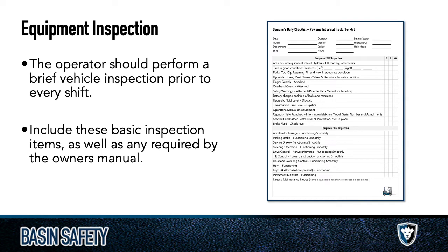All right, equipment inspection, vital. This needs to be done every day prior to the shift. If you have 2 shifts, you can get away with doing one for the day, but my recommendation is you just do one per shift, period. Now, if you have multiple people operating that equipment during said shift, one inspection will do. Each person doesn't need to do their own inspection. That's just doubling up on work.